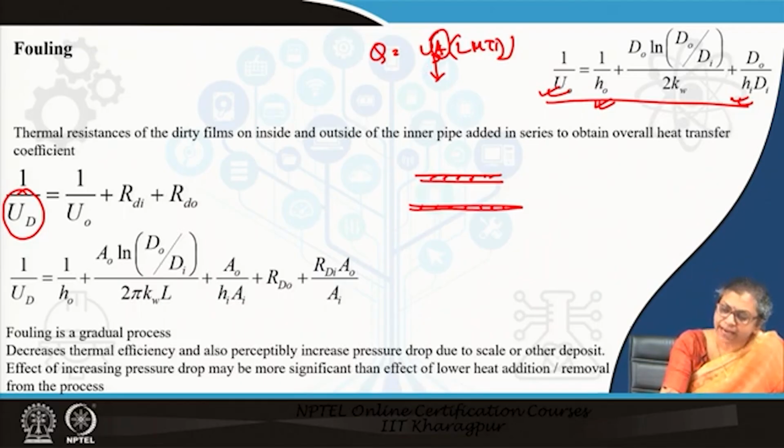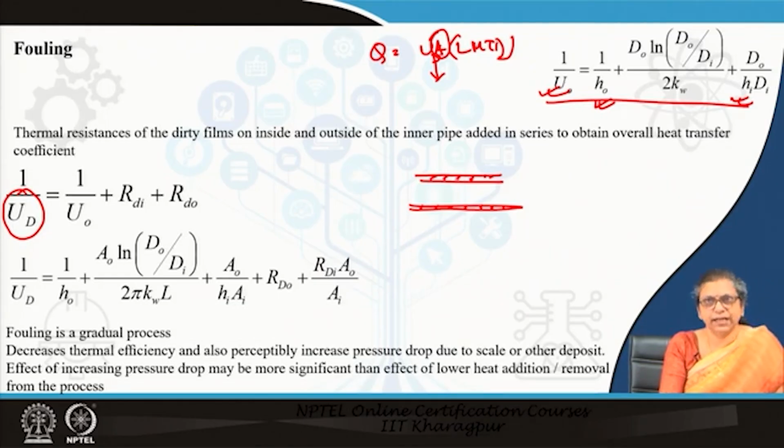This additional A will ensure that even with sufficient fouling, even with aging, the heat exchanger will provide the heat exchange that you want. The hot fluid will be cooled, or the cold fluid heated, to the extent that you want.